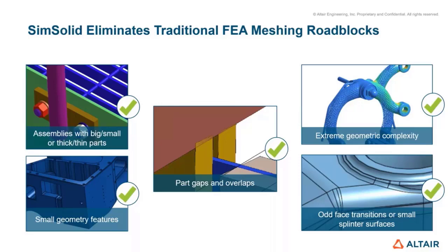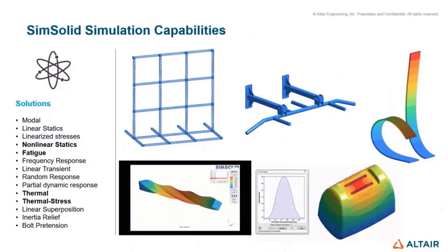Just a few words about the capabilities of the tool. In terms of the types of solution sequences it supports, of course, it does all the basic stuff like linear static analysis, modal analysis, and so forth, but it doesn't end there. It's also capable of doing nonlinear simulations, thermal simulations and linear dynamics simulation. So it's a quite broad range of different solution sequences that are supported.